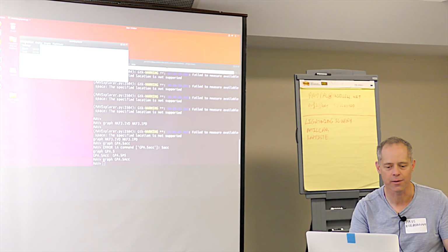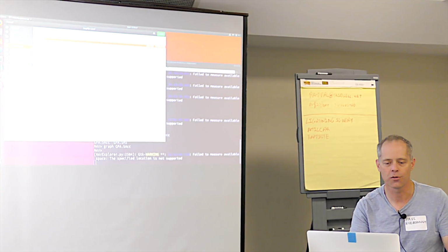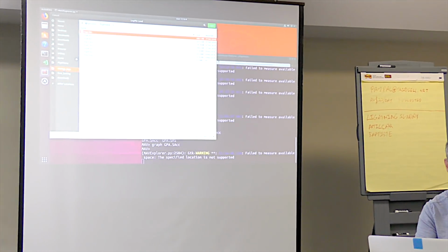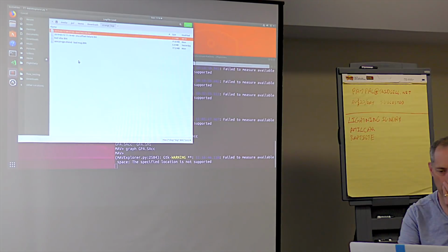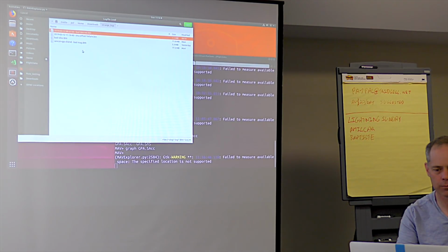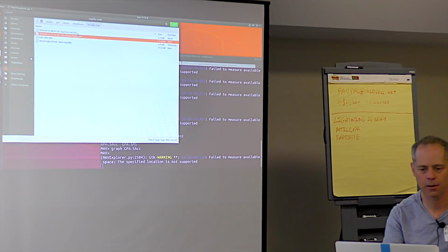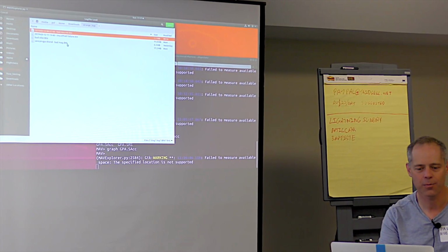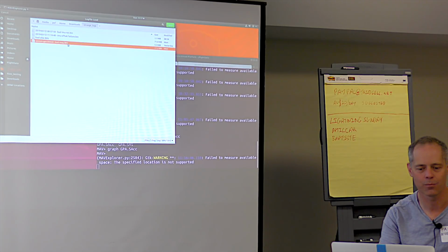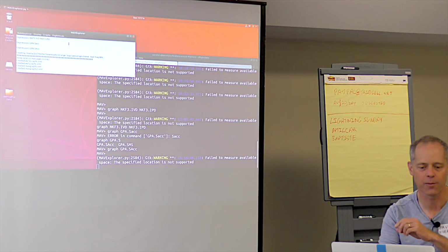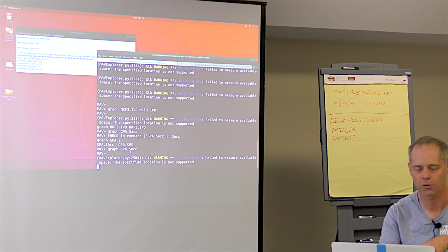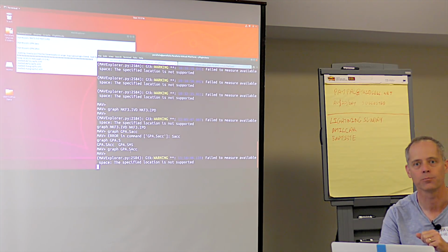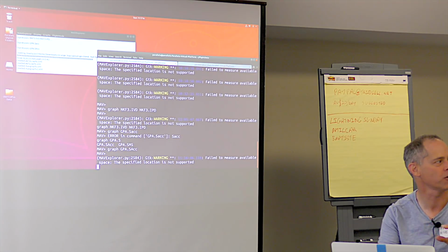So we've got another graph here that shows what happens with bad magnetometers. We've got an offset failure. Oh, that's the bad mag. I think that's the same log we looked at before, but this also had a second problem which was related to the magnetometer, not just GPS. There were two things going on with that log. And that's often the case. It's often not as simple as one thing.